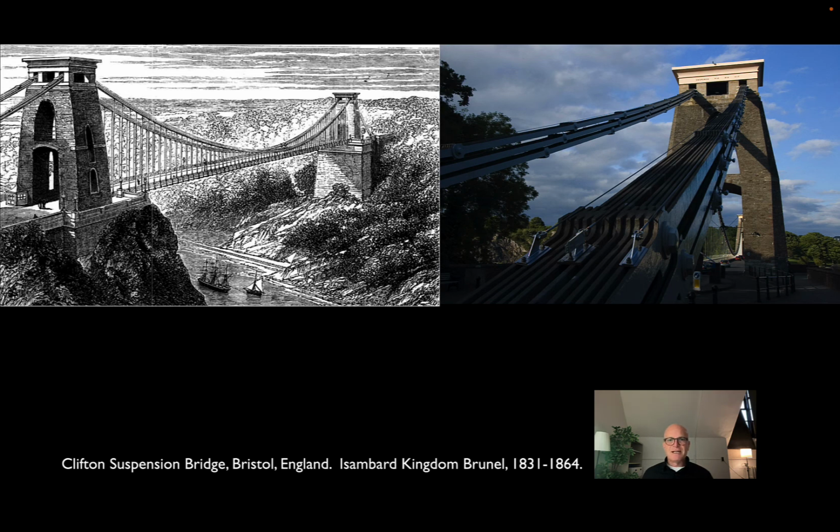Brunel also designed suspension bridges. This is one in Bristol, the Clifton suspension bridge that is still there, that has the same principle as the Menai Straits: wrought iron chains made up of very long eye bars bolted together, supporting the deck, and then you can see the cables run through the tower. They have to sit on a saddle that lets them move a little bit so the bridge can bend instead of break, basically. And then cables run into giant anchorages that are sort of wedged into the landscape.